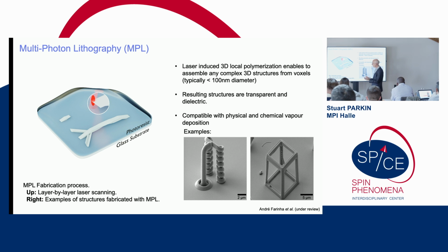Using this fantastic super resolution technique. Well, this is all Andre's work. And what he can then do is build structures. So you basically put a droplet of a photoresist, which has a rather complex structure, and you use a photoinitiator to initiate polymerization within that photoresist using a negative resist. So wherever the optical beam is, the focal point is, we polymerize it to cause a structure of the order